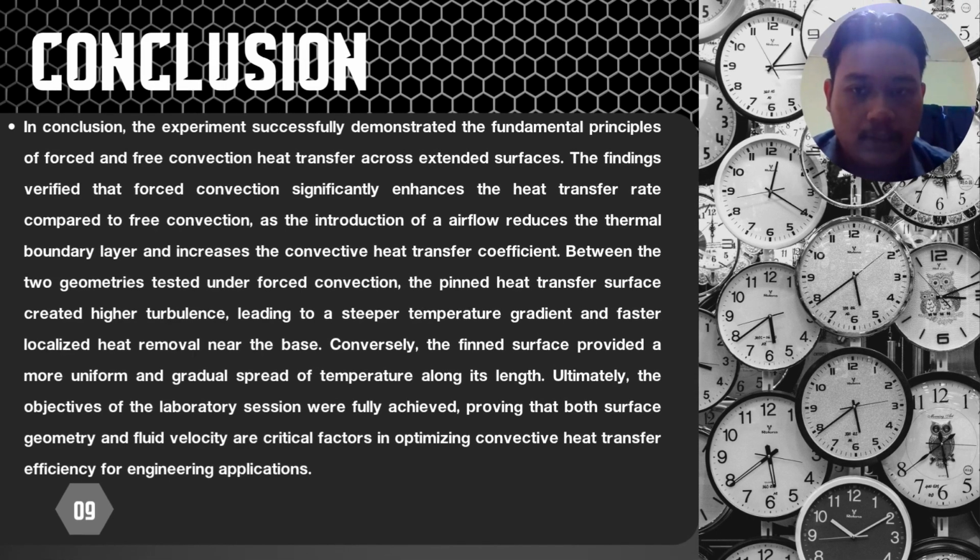Okay, last but not least is the conclusion. In summary, this experiment successfully validated the fundamental mechanics of free and forced convection heat transfer across extended surfaces. The results confirmed that forced convection substantially increases heat transfer rates relative to free convection, as the induced airflow thins the thermal boundary layer and elevates the convective heat transfer coefficient.